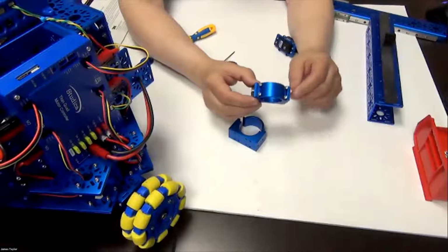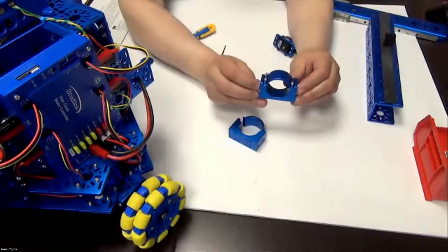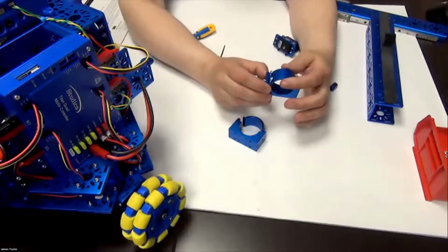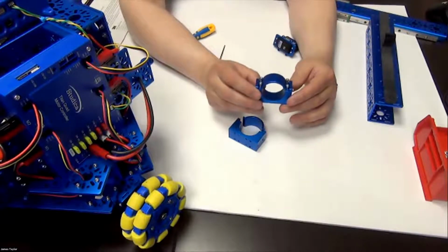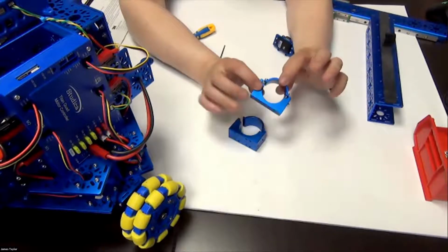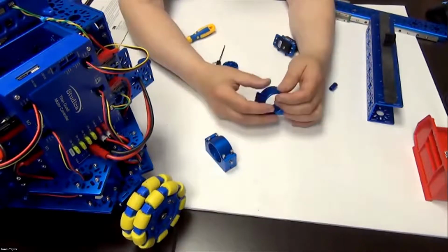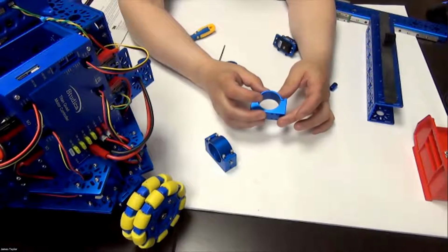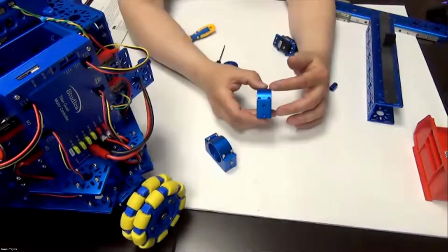This particular motor, if you don't want it to twist, you could actually put a couple of longer socket-headed cap screws through here to put a little tension on the motor. I don't think you're going to need to do that for what you're going to do. It's pretty good this way. And I don't think it's in the design anyways. So that's just that motor mount. Like I said, it comes in 2 pieces. And you're just going to put that on. So that's one of the newer things that you're going to use. And this is going to be used to mount that 60-to-1 DC motor for the A-frame, which is what we're going to use to drive the elevator up and down.